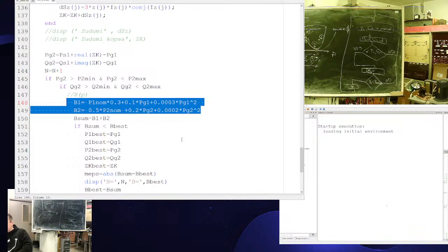They will give you an expected efficiency chart, but the real ones come from commissioning. The station should be checked for the full load range and get a signed and sealed document.